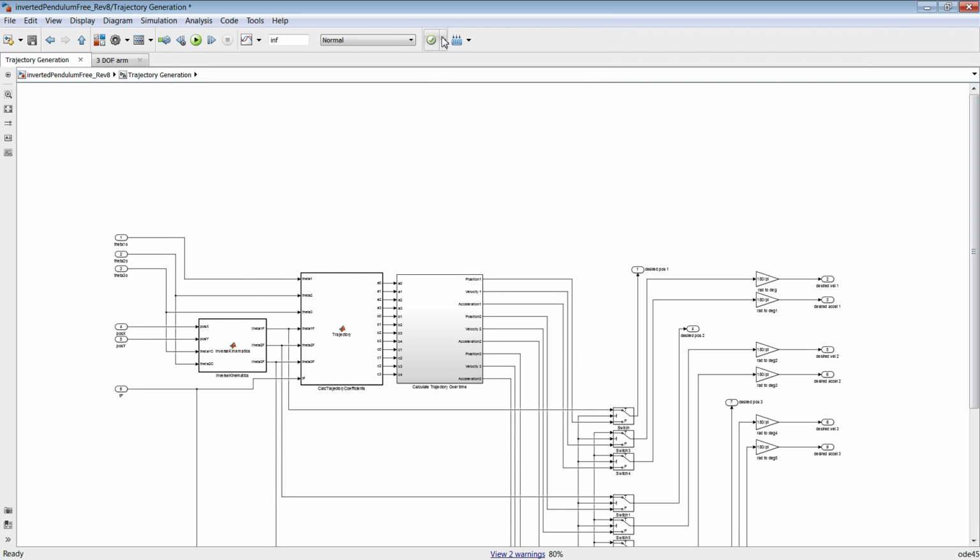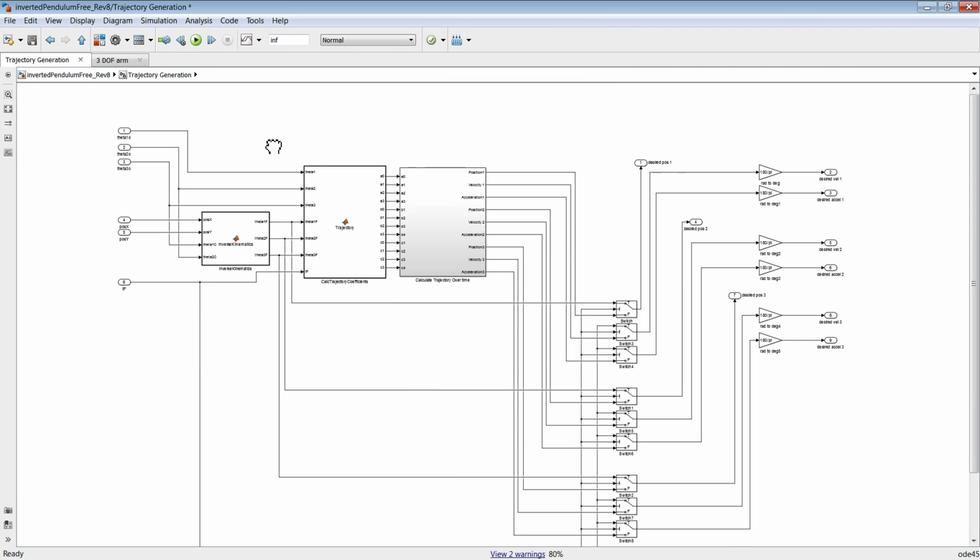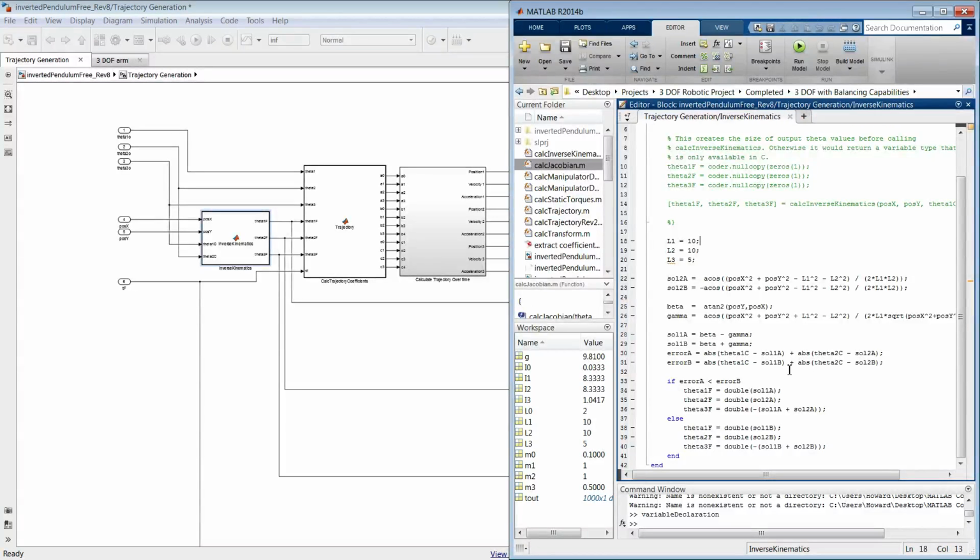Alright, so this system, the inverse kinematics, actually we use a geometric solution to solve how the configuration of our arms, or better said, the data values of our motors, to reach the target position. So since we're using a geometric solution, there's more than one way to reach it. So the arm could be upside down, or it could be upright.